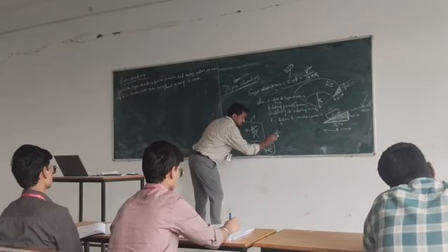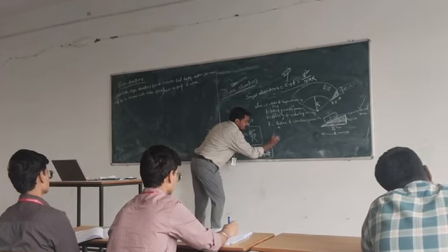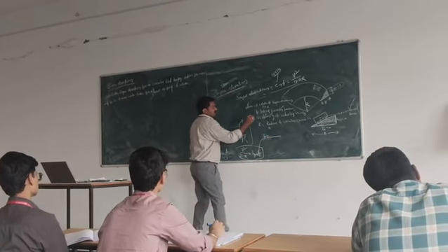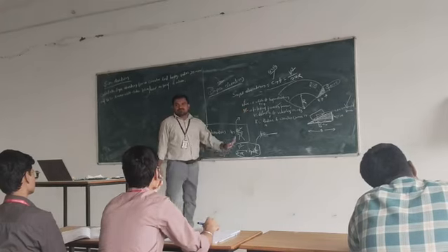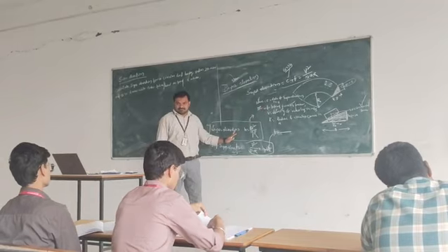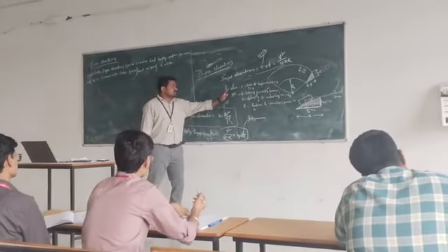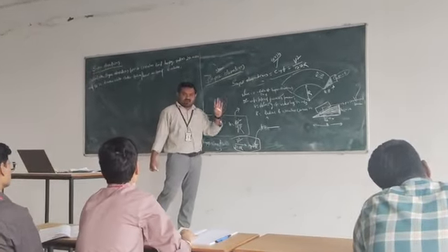In hilly areas, friction factors will be mentioned, but in those areas no friction factor is required. So this is our superelevation formula. Is that right? Now let us go to the problems. How will we work out the superelevation formula?